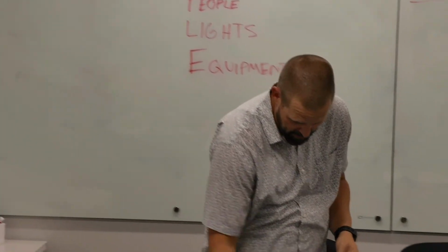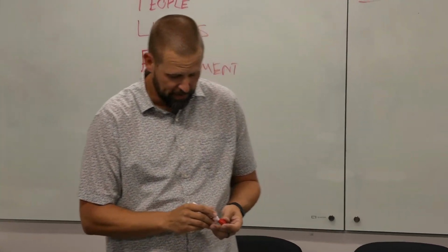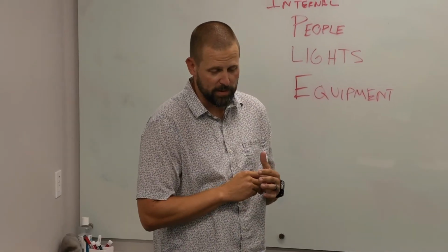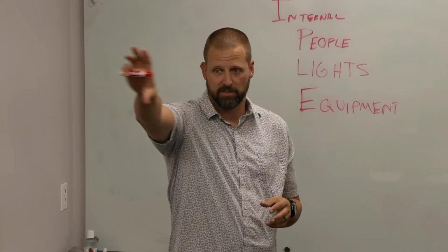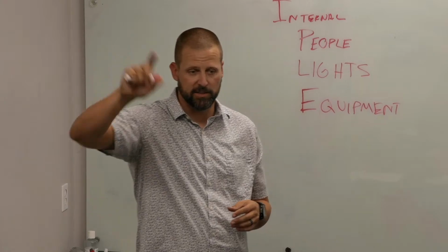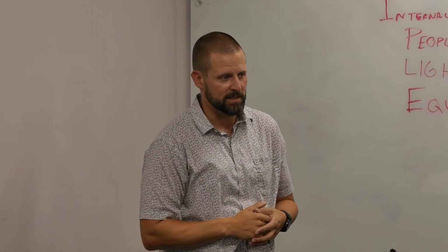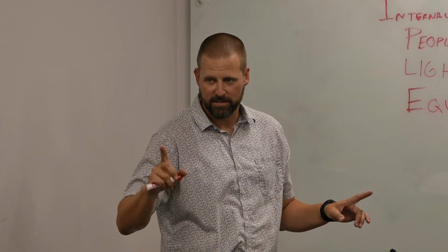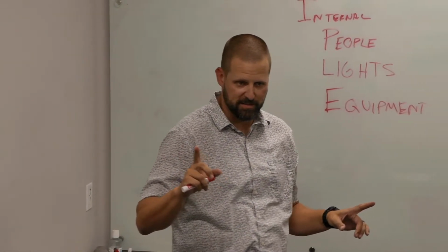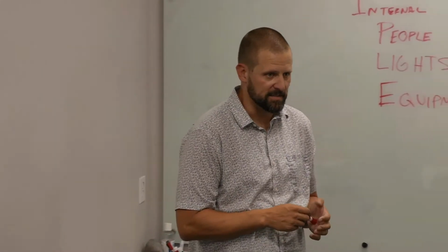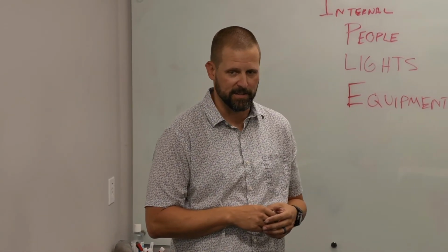Okay, first let's talk about, when we think through loads, the geometry is important. So the area of the wall or the area of the window that interacts with the outdoors is how we come up with our load. The temperatures are important. So the temperature outside, which we'll talk about some weather data in a little bit, and the temperature inside is going to drive our load. And then whether we are north facing, south facing, east, west, that's going to affect our load.